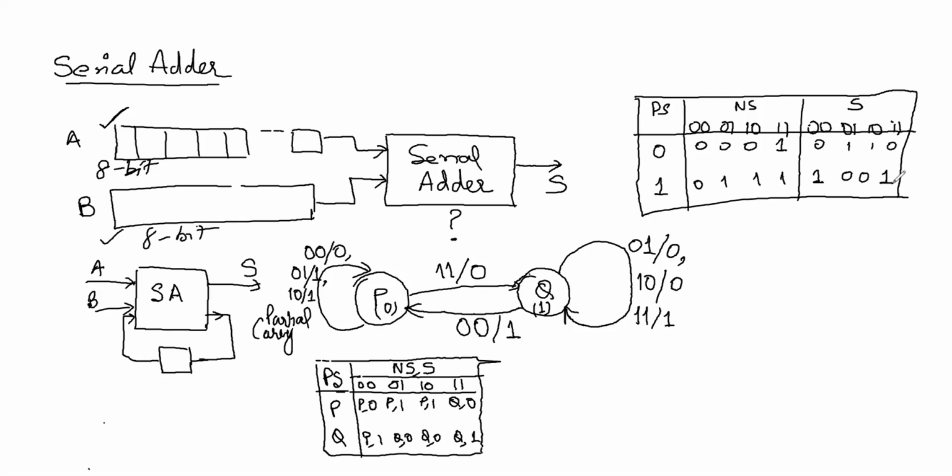Now you can also identify, since my state is a 1-bit state, I need only one flip-flop to design the circuit. One bit, one flip-flop, that is what we are designing. So I need to choose which flip-flop we should pick up. Let's say I can even pick up D flip-flop. So let me first convert this to a table where I can draw the excitation table easily.